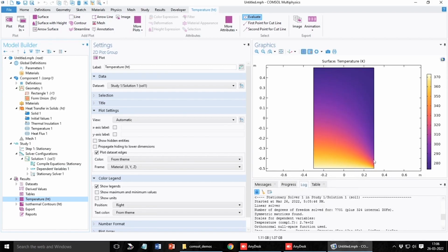Before trying to calculate the value at 0.2 meters above the right hand boundary, let us try to get an understanding of how to calculate the dT/dx value at a particular y point. These are very important post processing things. In the results, I find the post processing the most complicated, the harder bit.